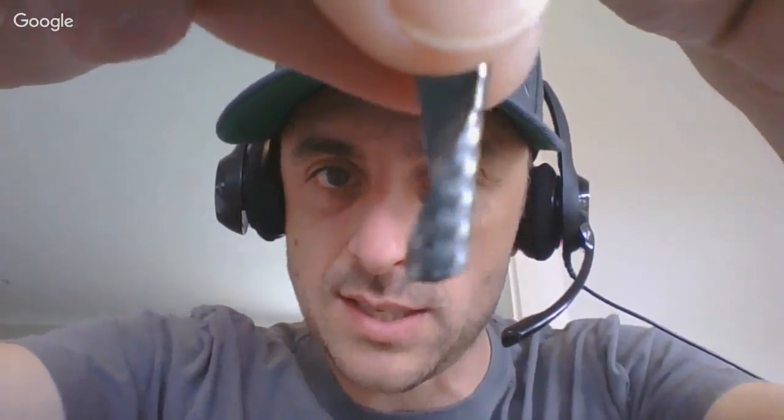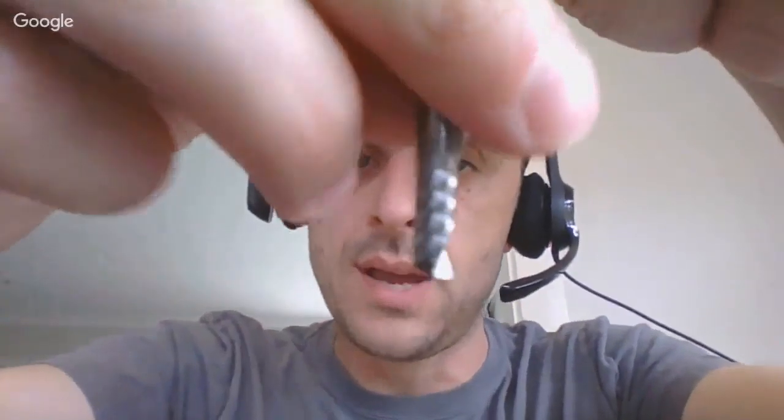Whereas if you have a look at an upcut, you'll notice that from the cutting edge, the flute is moving up on that angle relative to the cutting edge. And so that's now going to lift the material up. The lifting effect is better for chip evacuation. It's pushing it up and out those flutes, but you have that disadvantage of it lifting that top surface. So hopefully that answers Lindsay's question. But if not, we can talk about it more.